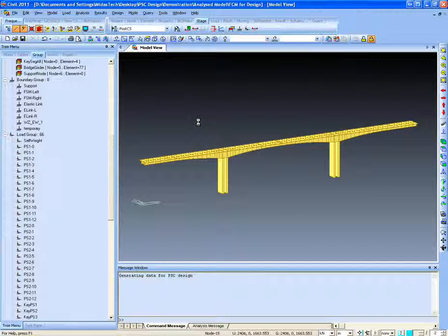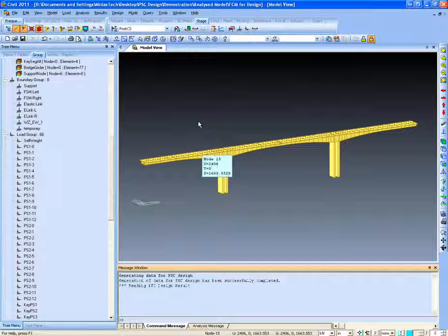Once you design the bridge, you can see the flexural moment of resistance, the shear resistance, and the combined shear and torsion, and the various serviceability limit states such as the stresses in the tendons, the stresses in the reinforcement bars, the stresses in the concrete, and whether they are in the allowable range or not.